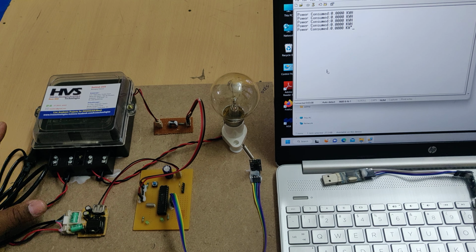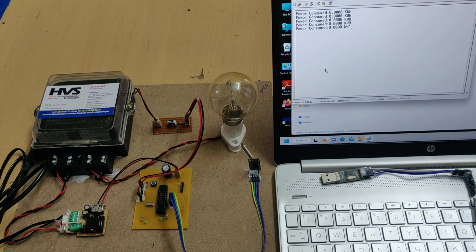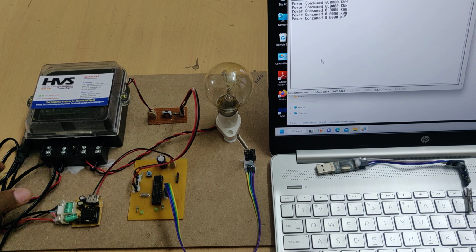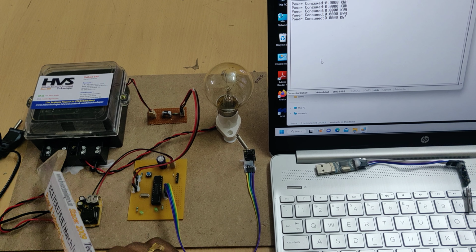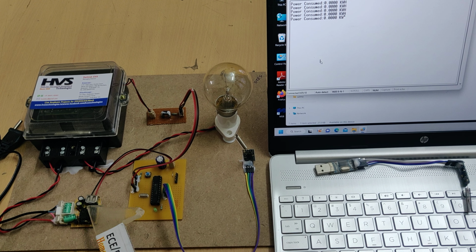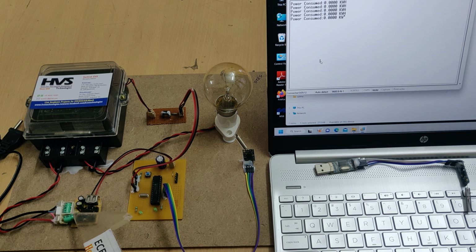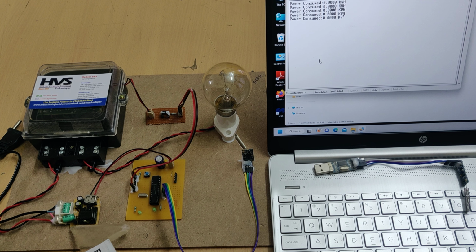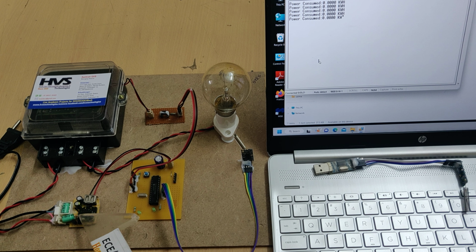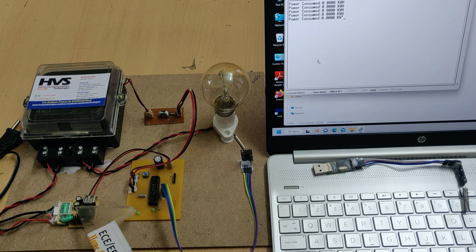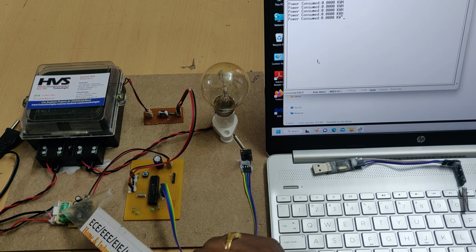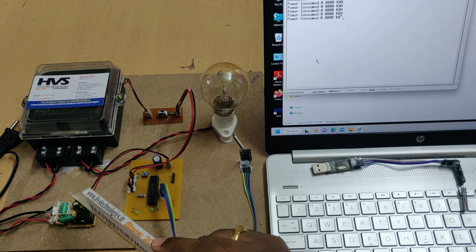Coming to the hardware section, we are providing 230 volts AC input to the energy meter circuit. That is the energy meter input, and from there we distribute it in parallel to this regulated power supply board. It has 4 stages: transformation, rectification, filtration and regulation. Transformation steps down the 230 volts AC to 12 volts AC, rectification converts AC to pulsating DC, and the filters remove the pulses and we get pure DC voltage,